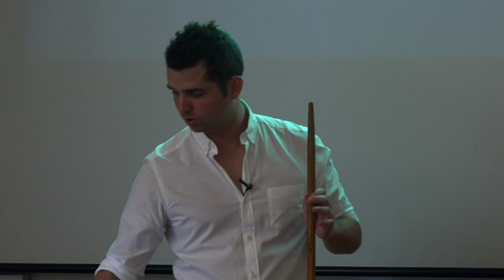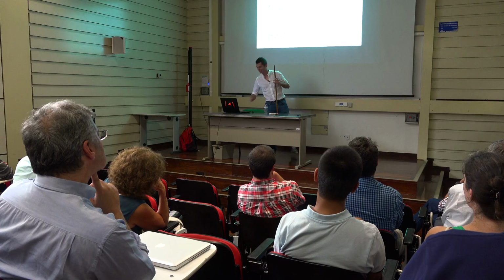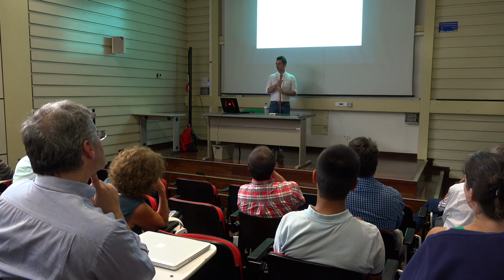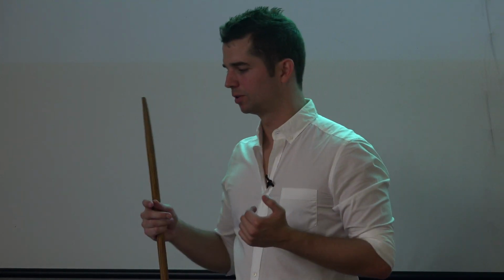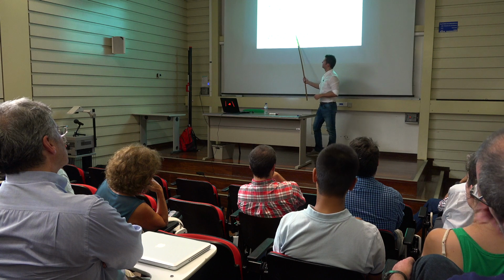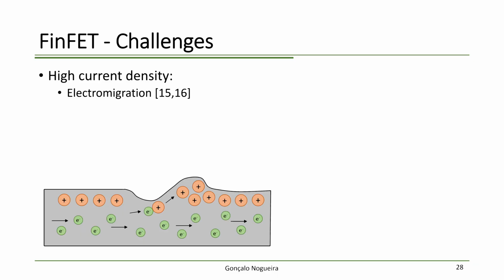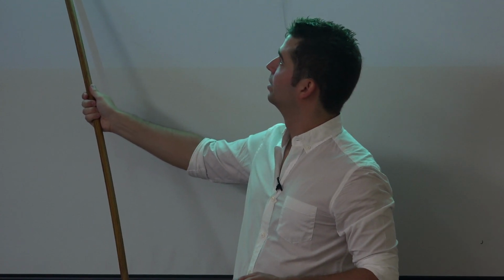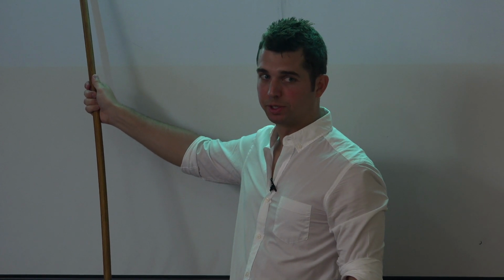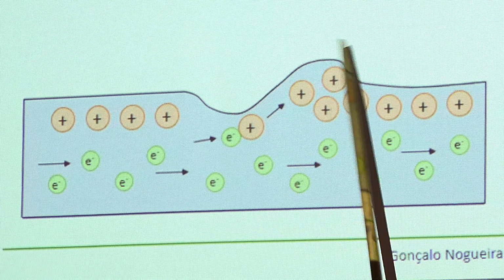So, first of all, what is electromigration? When you have a real circuit, it's not just the transistors. You need metal lines to connect all the transistors, and you have multiple layers of metals. And here you have a metal. Throughout time, you have currents flowing through the metal back and forth. But from time to time, you have an electron that comes with such strength that it dislodges the atom from its place. And it can cause either voids or hillocks.